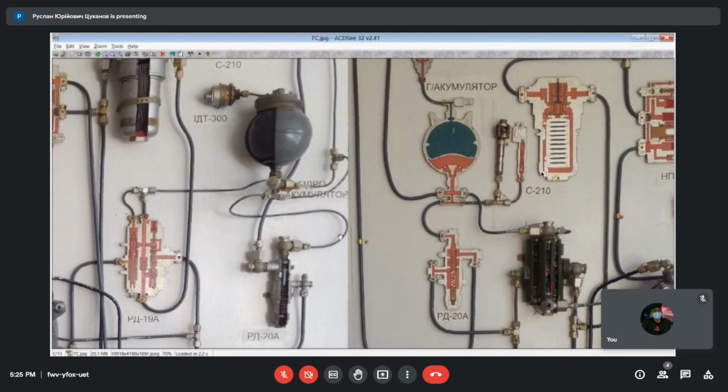Any airplane, any helicopter has the most critical devices without which you will lose control immediately and it will be an immediate crash. In this airplane, it is spoilers control and stabilizer control, which provide pitch control and roll control. As for other devices, they are assumed to be lower priority or secondary consumers, and so they are supplied with hydraulic fluid via priority valve. What does it mean?